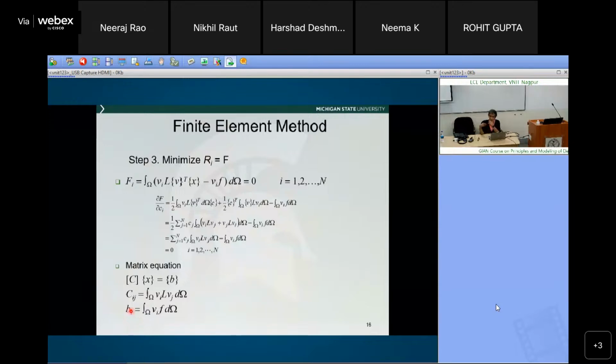In most of our models with just eddy current or flux leakage, this is enough because of the continuous excitation in eddy current, you just solve for the phasor, and once you get this E field, you can multiply by e to the j omega t and get your time domain solution. For a single frequency, there's really no time variation involved.